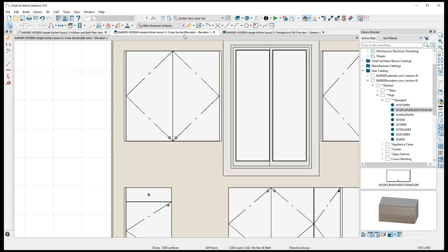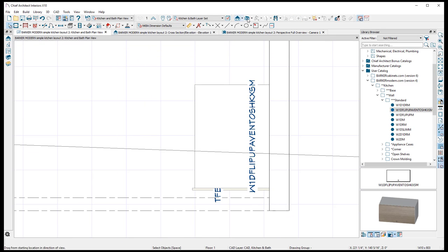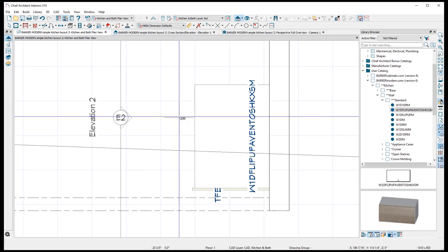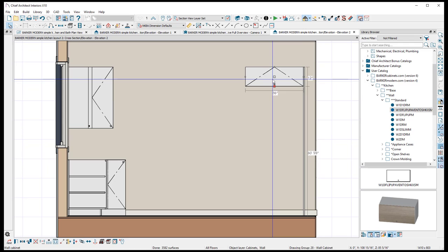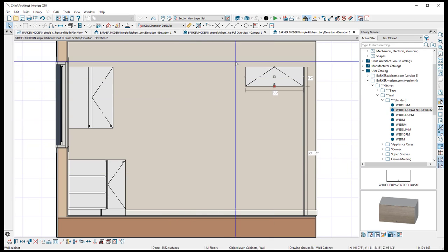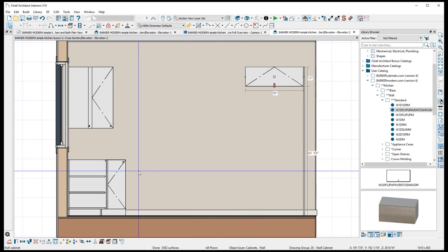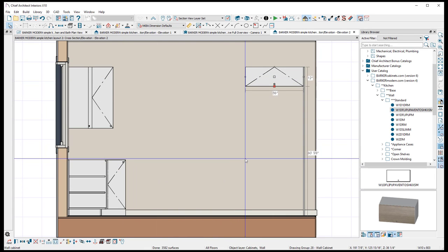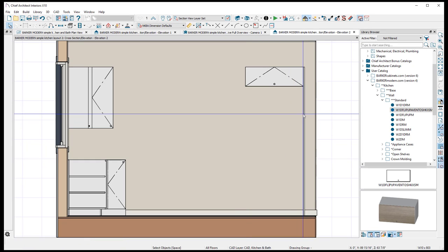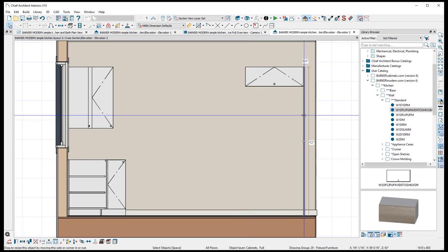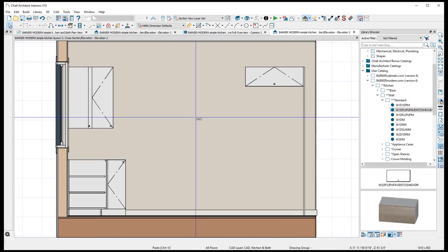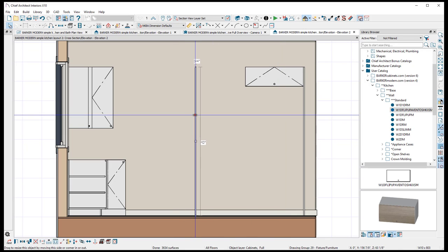And most people look at that and say, why would you want a 26-inch depth tall cabinet? That's because a 26-inch depth tall cabinet is enough to the point where, say, this tall stack that is going to be here, this countertop can run into the side of the end panel there, and it's not going to have this little nub sticking out. Having the little nub sticking out is not good at all because it looks odd, and it's more of a thing that standard cabinet makers have to deal with because they don't make their cabinets deeper than 24.